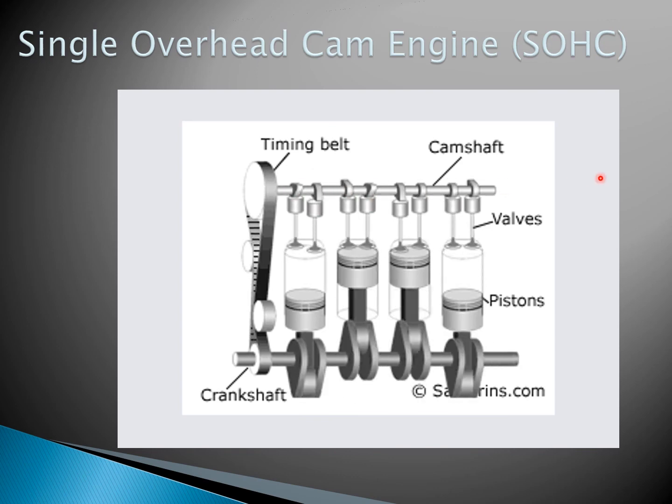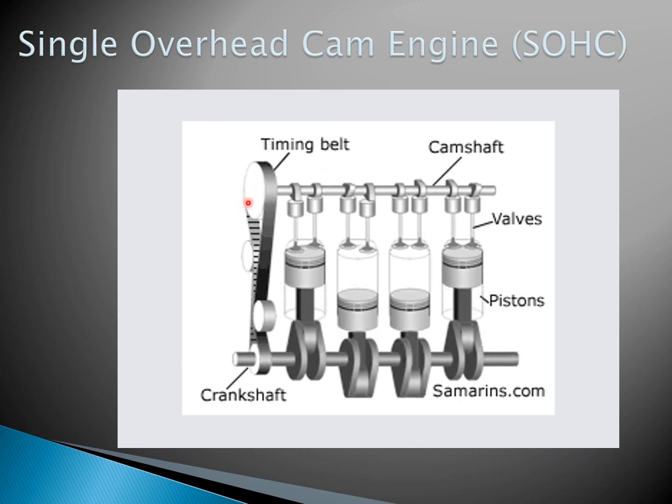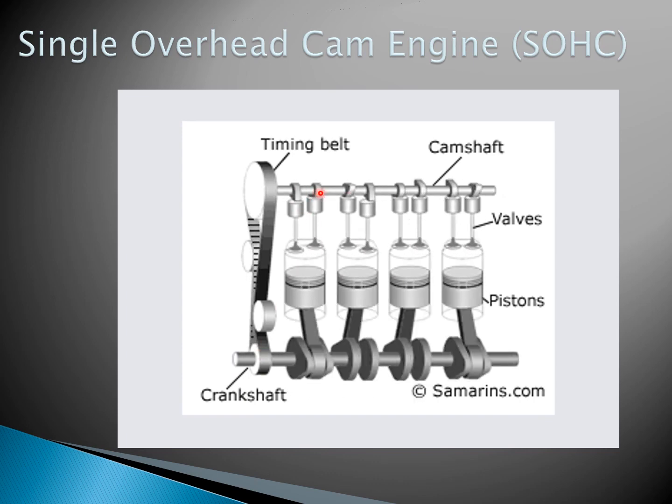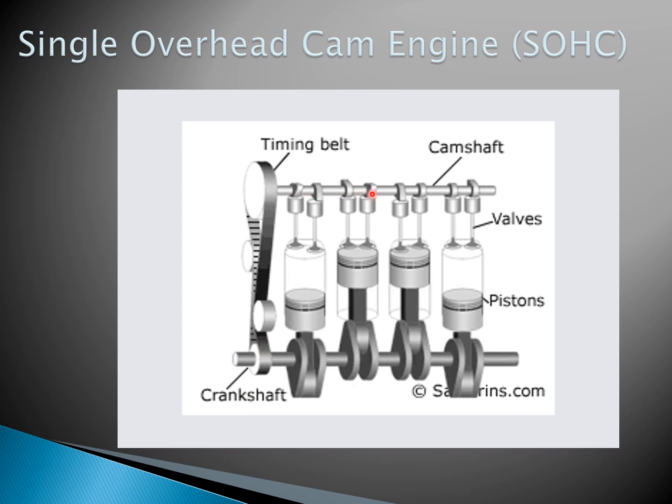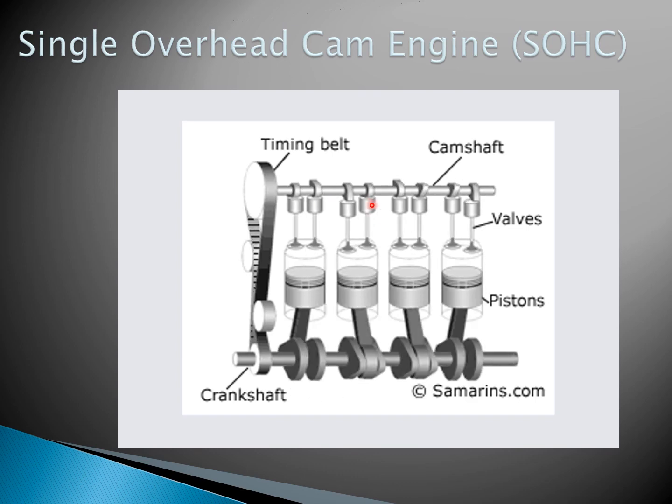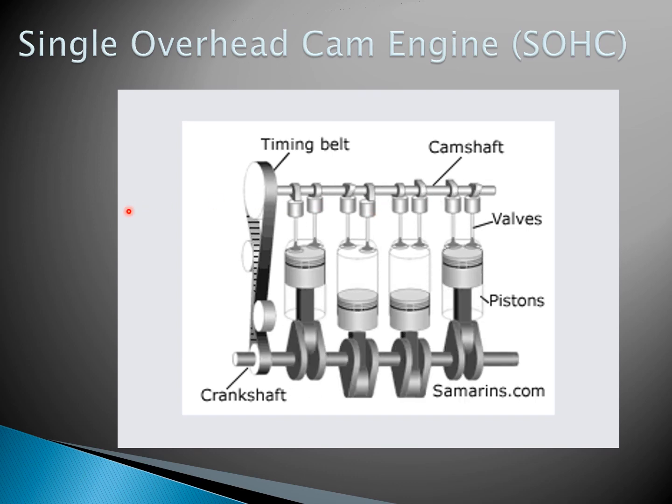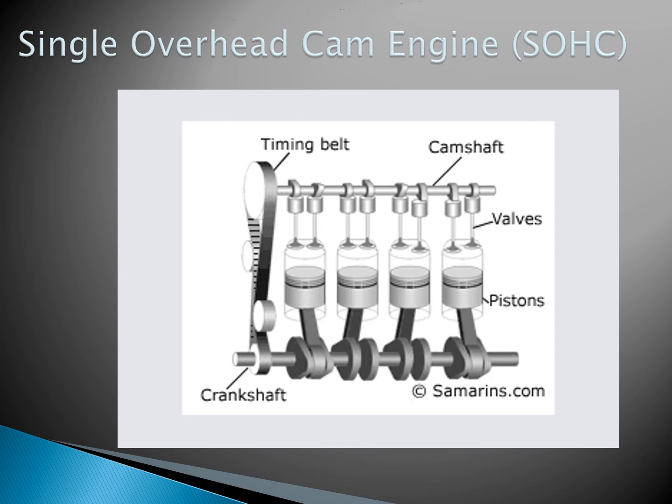So you see here your cams on top. Notice the camshaft pulley is larger than the crankshaft pulley. And these would be the egg-shaped lobes that push the valves open, and then the springs close the valves after they've been opened.